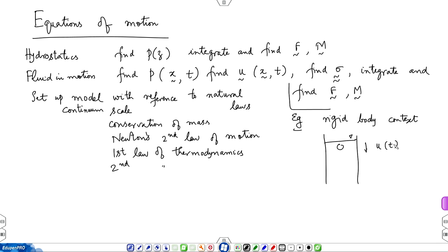Then there is buoyancy acting on it, and then there is also the stress distribution over the surface of the object because of the surrounding fluid, whose resultant, like the resultant you have calculated in case of hydrostatics, will essentially give rise to a form of resistance. Okay, why should it be resistance? That we will see later, but you can also think of second law coming into picture, that as the object is going down, the fluid exerts resistance to its motion.